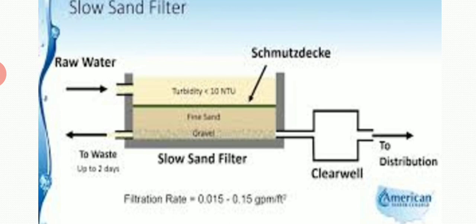So this function is to remove the particulate matter by electrostatic action exchange. The charge of filter media neutralizes the charge of the flock, thereby permitting the flock to be removed. That means the charge of the filter bed is positive and the charge of the flock is negative. So they exchange the ions and make the flock settle down. During this process of exchanging ions, the impurity settles down and we have pure water trickling down.